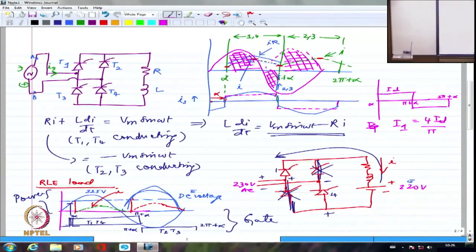And the fundamental is normally sinusoidal in nature, because Fourier expansion essentially tells you that any periodic waveform can be expanded into several sinusoids consisting of the fundamental, second harmonic, third harmonic, fourth harmonic until the nth harmonic. Right? So, the fundamental is a sinusoid in its own right and it is going to have the peak value of 4Id by pi. If I try to draw that fundamental corresponding to this, it may look something like this. It should actually have a slightly higher value maybe, and